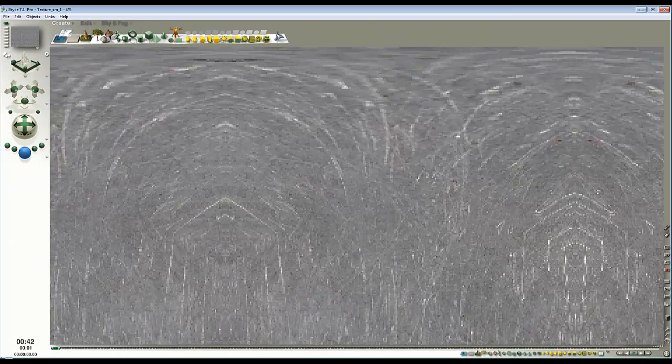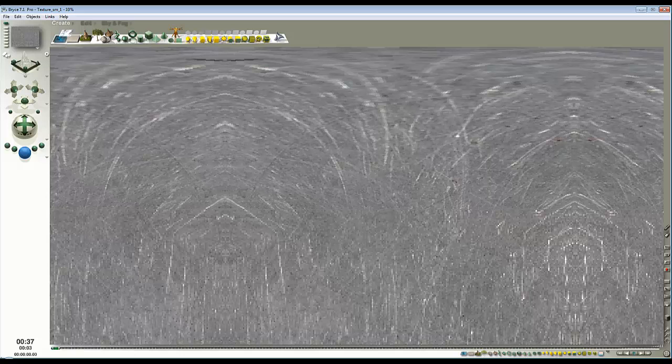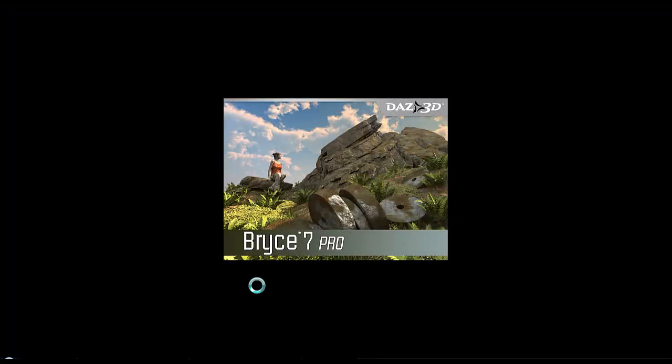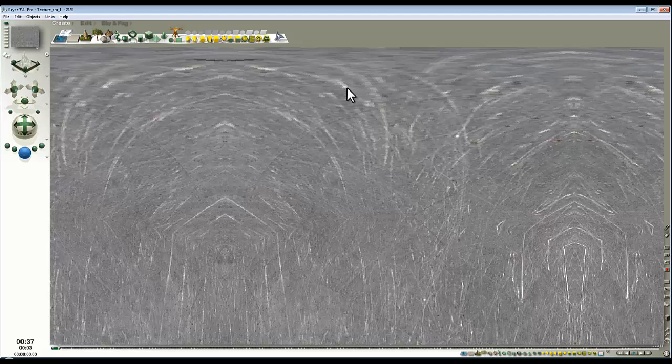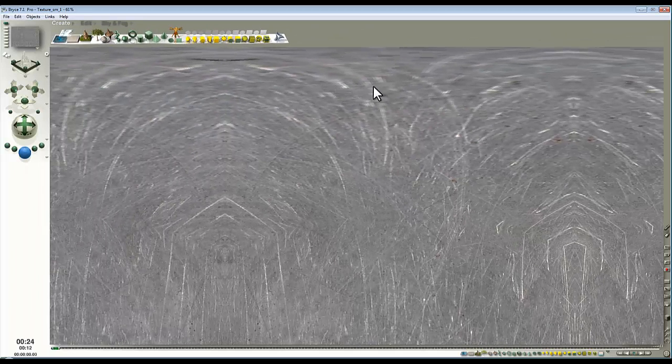Okay, while that's rendering, which is going to take, I don't know, a minute or so, I'll launch a new instance of Bryce. Go back here and point out, you see this pixelation at the top where it's stretched by the spherical mapping lens system. That would be less obvious if we'd got picture interpolation on, but because none of these images tile, all I've got to do is accept that this will be compressed and you won't notice this. Otherwise the interpolation loops around some of the image from the back edge, and where these seams are between the objects, they'll become obvious because of the wraparound.